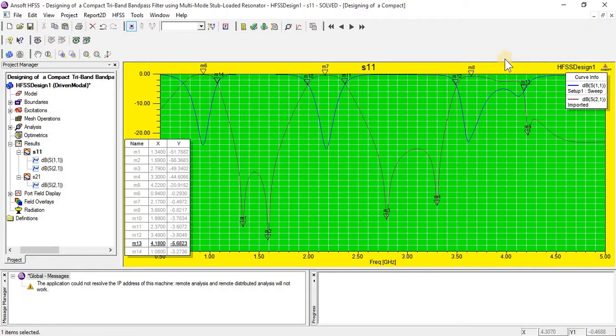Similarly, M13 is at -15 dB. Because of mismatching, a very big mismatch occurs here. That is why our graph is not made properly. But actually, we take fractional bandwidth at -3 dB. Similarly, we find insertion losses this way and transmission zeros that way. In a coming tutorial, I will discuss how to create a transmission zero at our desired position.